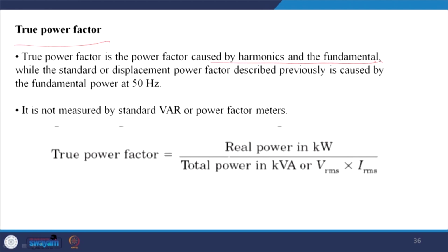While the standard or the displacement power factor described previously is caused by the fundamental power at 50 hertz, and it is not measured by standard VAR or power factor meters. So, for true power factor we require to take cognizance of the harmonics.